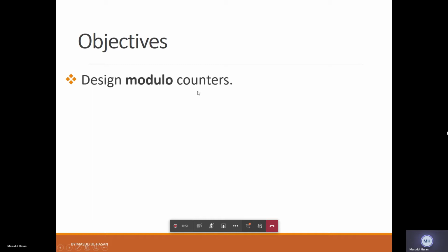In your case, as one of your friends said, you are not going from 0 to 99. You are going to make 0 to 59. So 0 to 59 means here you will have mod 10 counter, and here you will have mod what? Mod Five? Six? Yes, six.